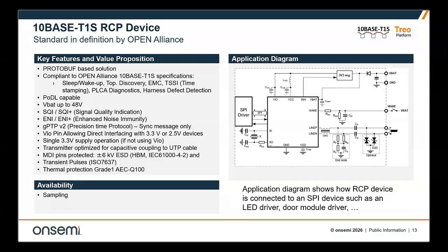So the flexible VIO pin lets it interface directly with 3.3 or 2.5 volt devices, and it can also run from a single 3.3 volt supply. So the transmitter is optimized for capacitive coupling to UTP cables, and the MDI pins are protected to plus or minus 6 kilovolt ESD. So with grade 1 AEC-Q100 thermal protection.